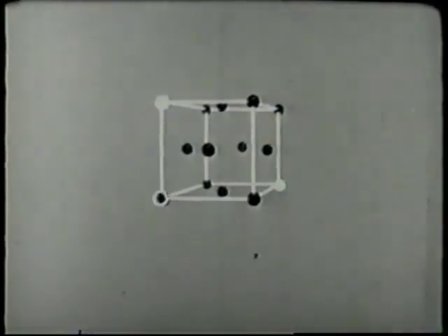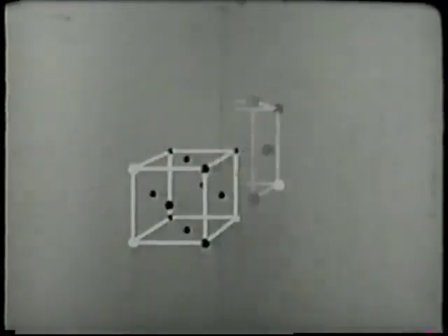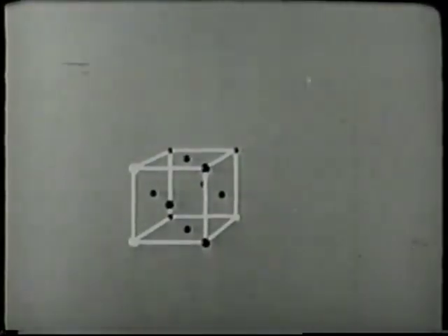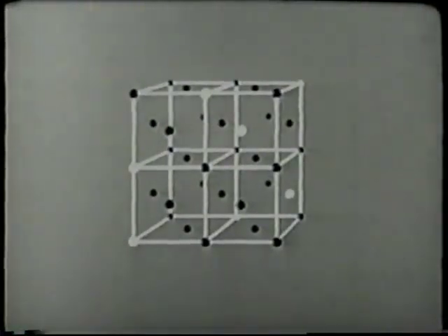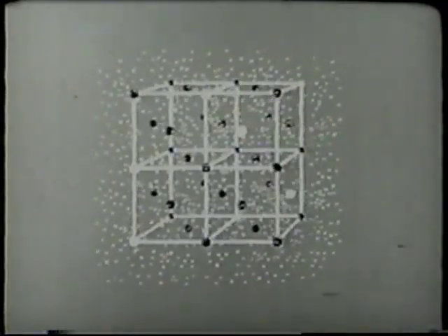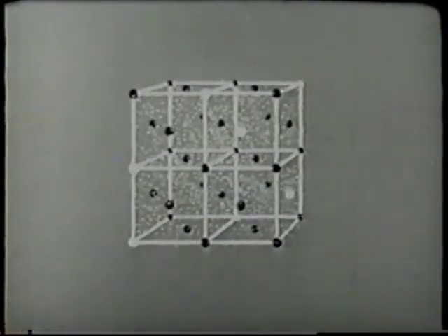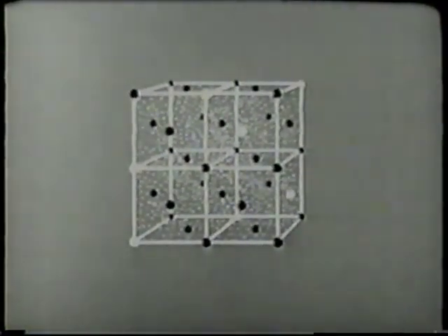The atoms of the alloying element are dispersed throughout the aluminum, displacing some of the atoms in the aluminum crystal lattice. The second is the formation of an intermetallic compound between the alloying element and the aluminum. In the case of alloy 24S, the compound formed by copper with aluminum is copper aluminide, or CuAl2.